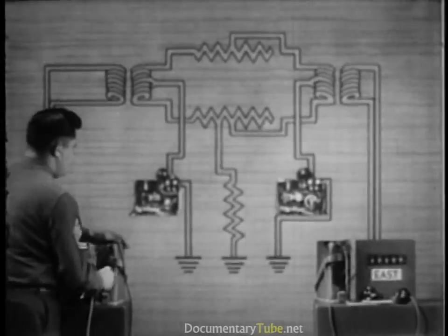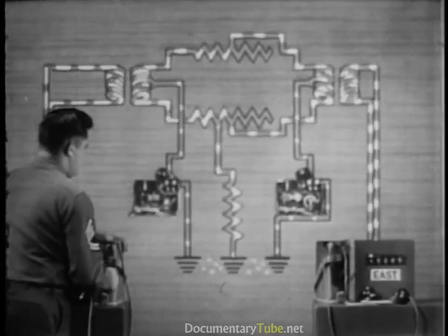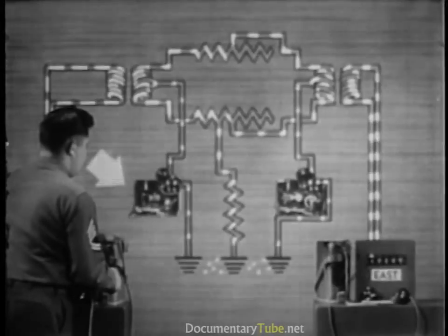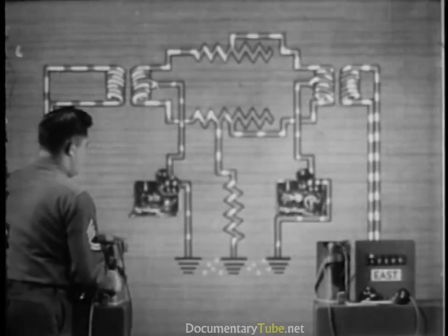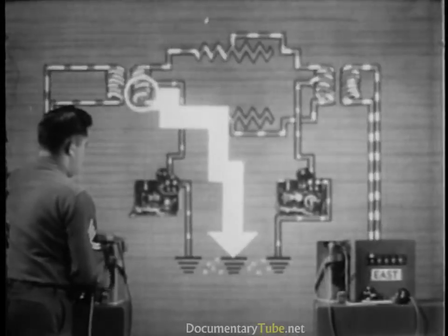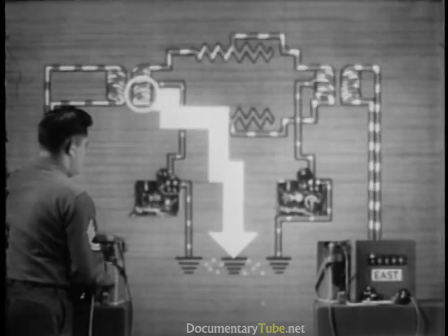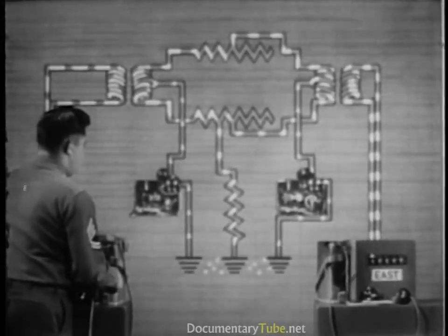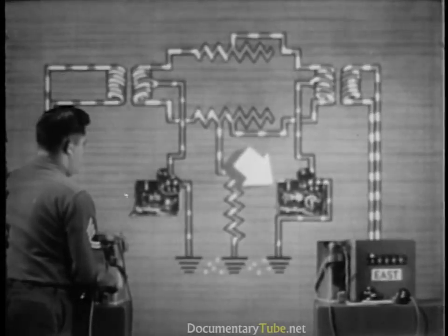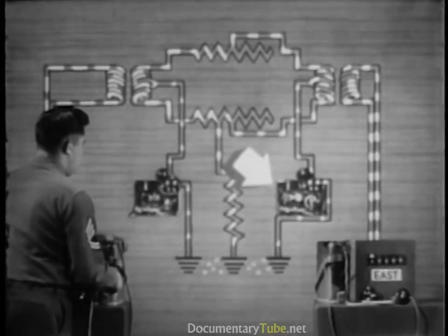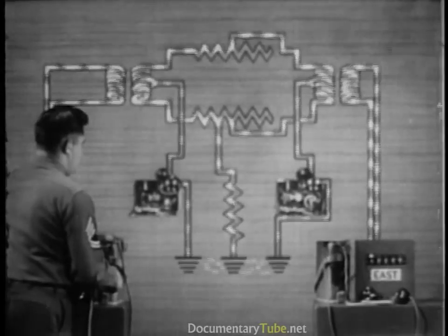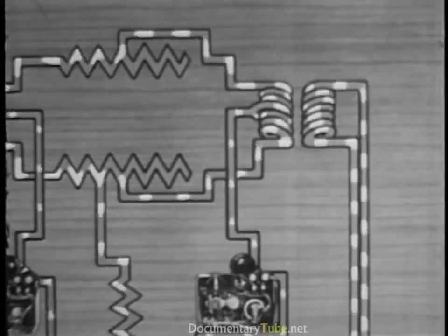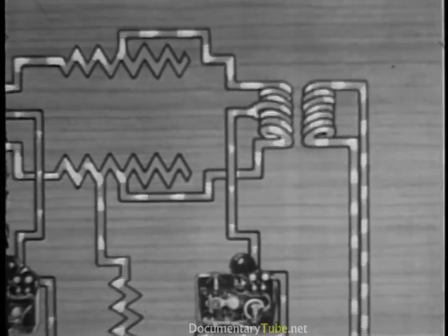When we ring on the telephone channel, some ringing current flows through the near telegraph set because the lower half of the repeating coil has a shortened path through the accidental ground. This causes an unbalance in the normal ringing path, so that a small amount flows through the far telegraph set too. Because of this, the ringing current delivered to the far switchboard is less than normal.